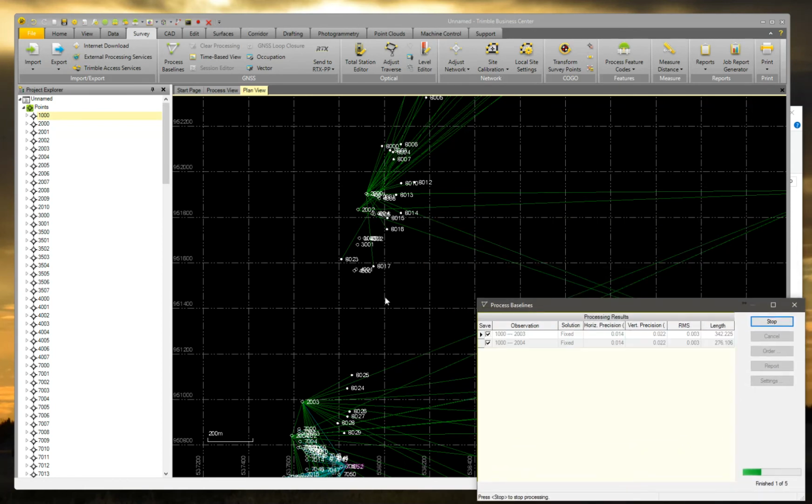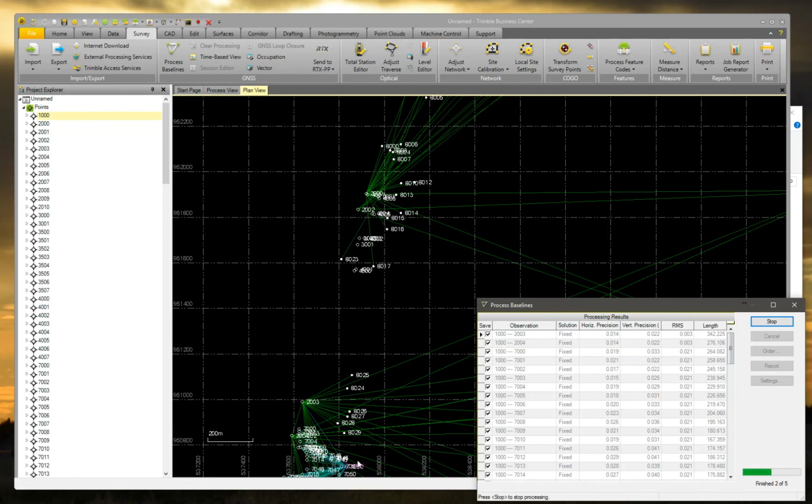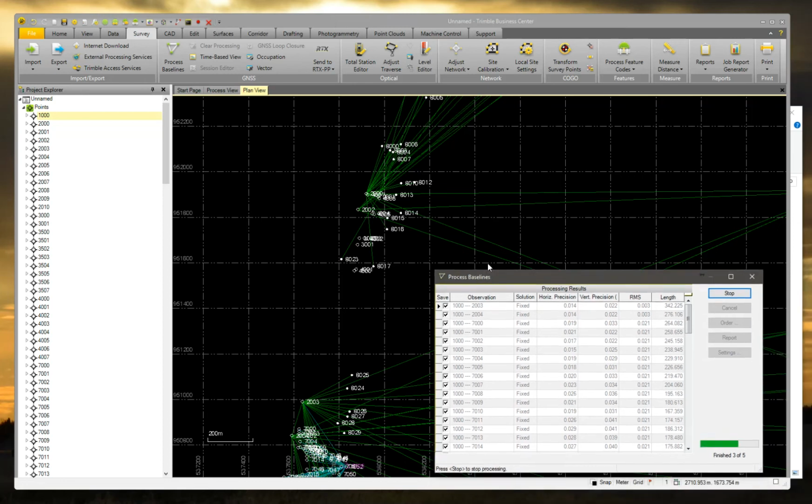It looks like what happened was that the base station was running in the morning. You guys did some GPS shots, collected data with the rover, and then at some point the base shut down. And because of that, you keep measuring shots, and so we don't have those GPS vectors here. So these coordinates are floating. They're not going to be very good. They'll be plus or minus probably 15 meters or so.